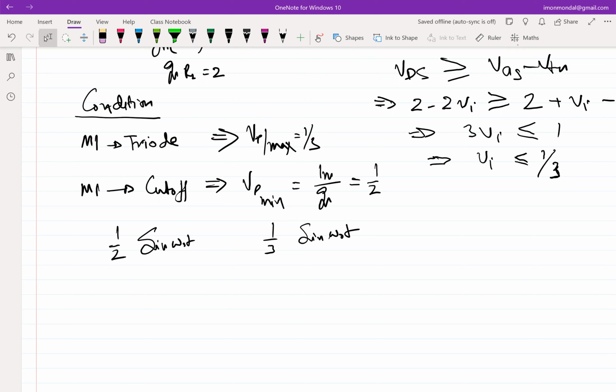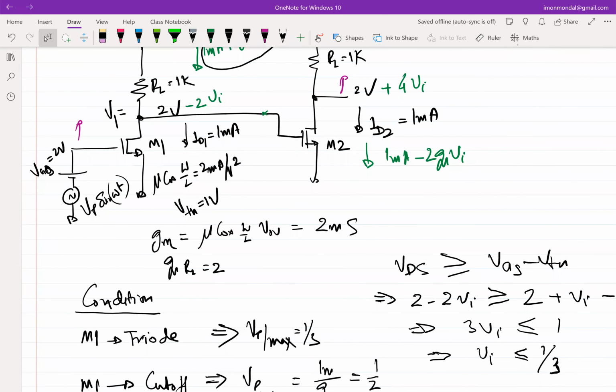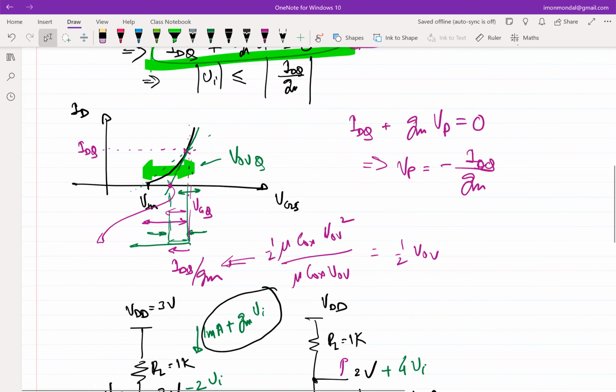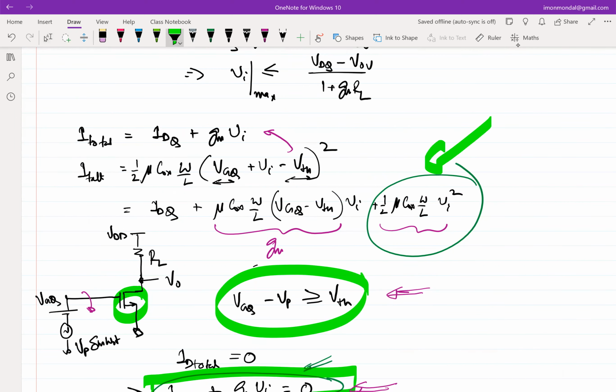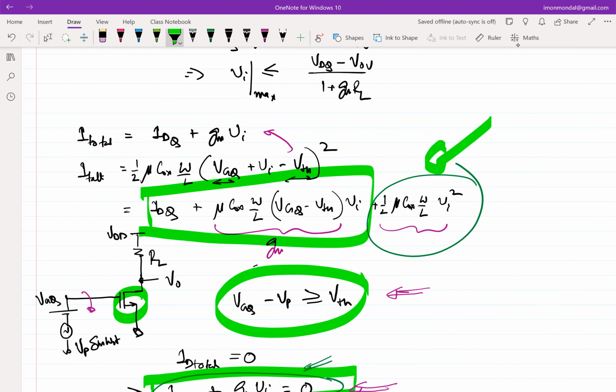One question, sir. When this current is becoming 0, still the gate voltage is there. Right, yeah. Current is 0, but the gate voltage is there, meaning you have incremental gate voltage, and the transistor is still in saturation. How is the current getting to 0, sir? So it's an approximation, right? Current is going to 0 because we are essentially saying we will neglect this term and say that the total current is this. If I take the squared term, then whatever you are saying will come into the picture also. So that's the whole point, right?